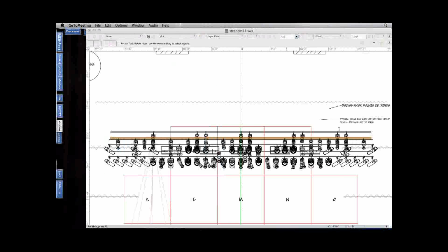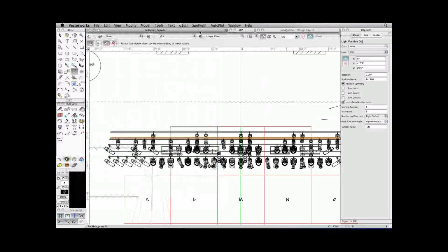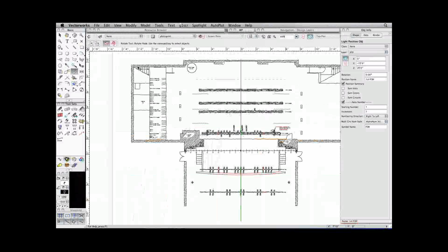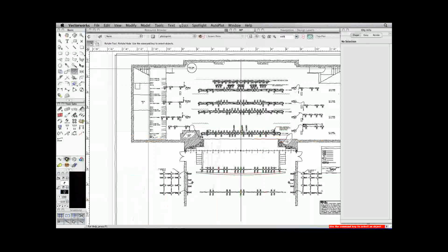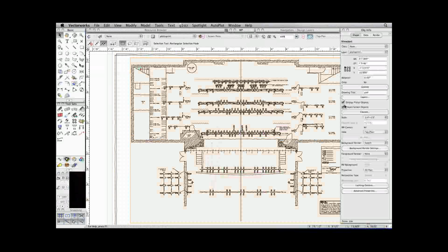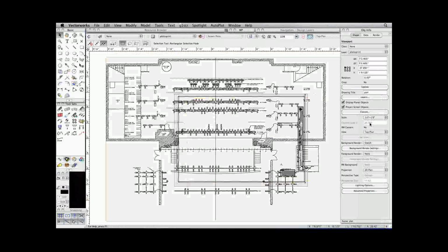When the viewport is created, can the scale be zoomed? Absolutely. And that's one of the joys of viewports. We go back to our sheet layer. This particular viewport, if we looked at this, for example, and decided, well, that's too big for the page, I can change the scale as easily as, well, now it's going to be twice the size, as easily as that.